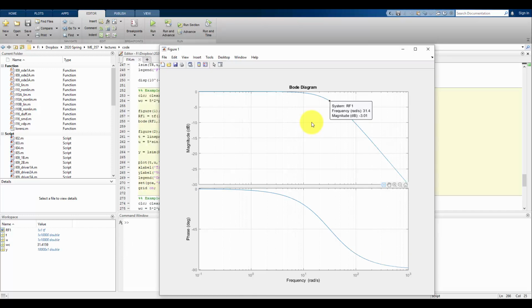Now when we look at the Bode diagram for this transfer function, again, we've identified the cutoff frequency, but notice in this first order filter what's happening here. Ideally, the cutoff frequency is going to be the marking point between the frequencies we want to keep and those we want to get rid of. So in an ideal filter, what we would love to see is that the magnitude is really flat at 0 decibels and then makes a very sharp decline, pretty much a vertical line, and then has very, very low decibels for everything above our cutoff frequency. That'd be an ideal filter.